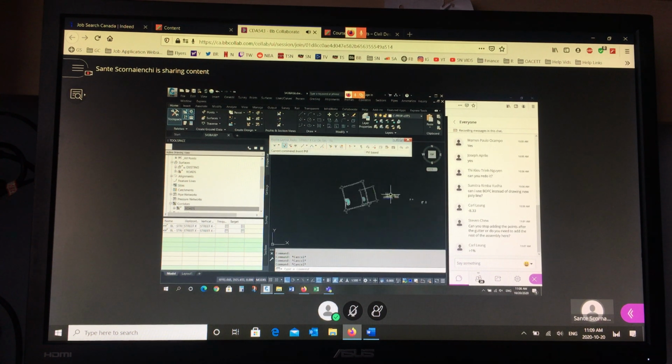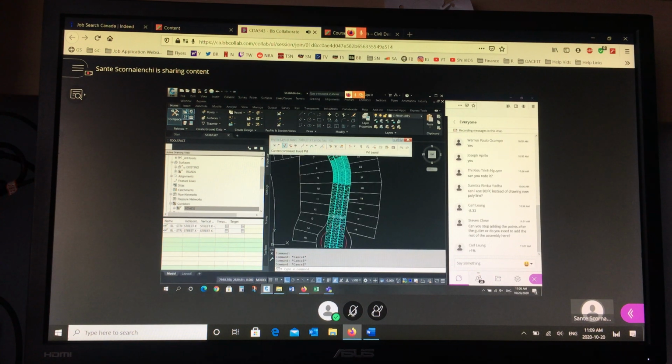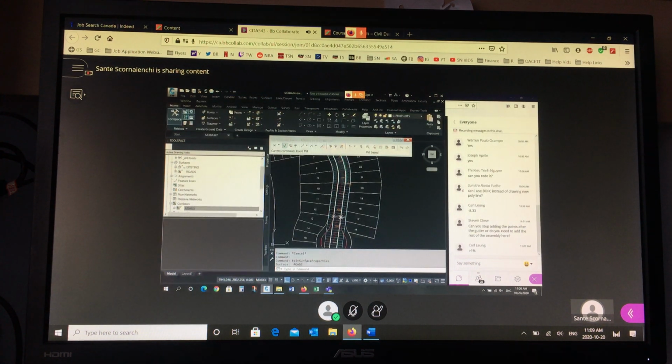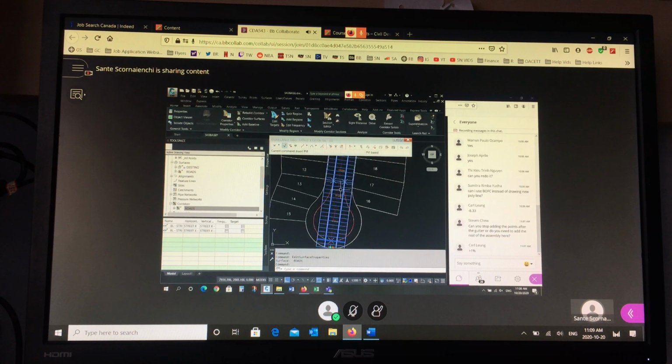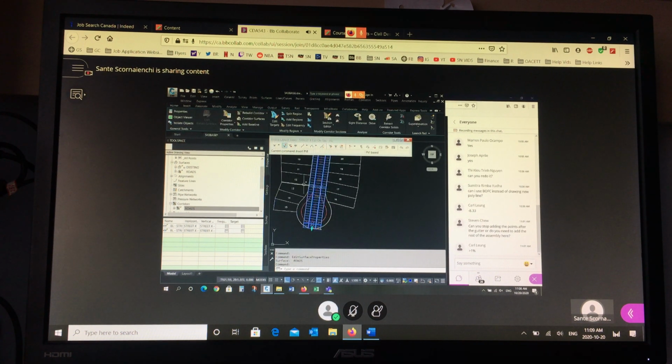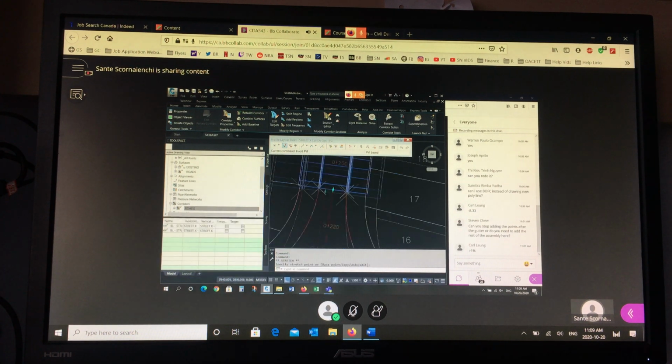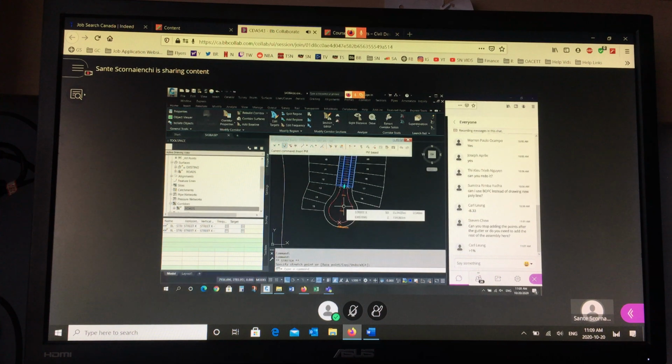Okay. Let me turn off the surface for just a second. Turn off the view. And there's the corridor. Now you've got a couple of options here. You can split the region so that you can turn this off, or you can delete it. The way the PDF demonstrates it is to create a region and turn it off. So this is what I would do. It actually drags it back. You can take this and say, okay, only build up to this point here, because everything else is wrong. That's one way of doing it. I think that's what's in the PDF.